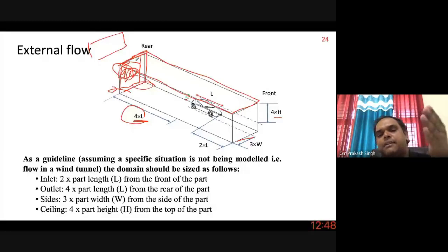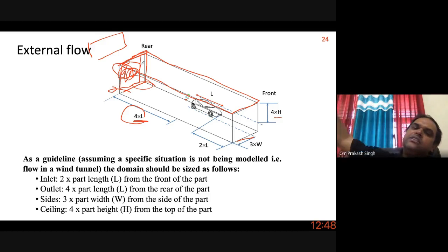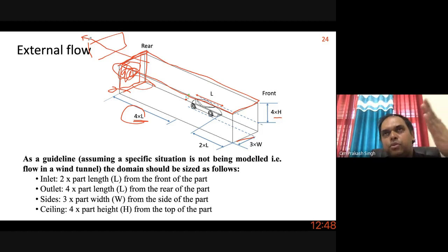If there is a reverse flow and that surface has a fixed boundary condition, then the software, or the physics of the flow, will try to maintain the same pressure because you have imposed a fixed pressure externally. Since it's not possible because of the reverse flow, maintaining a constant pressure is very difficult. So it will show a lot of divergence, a jitter in your residuals in the CFD. So what to do? You just extend the surface beyond the distance where the flow will be almost stable.